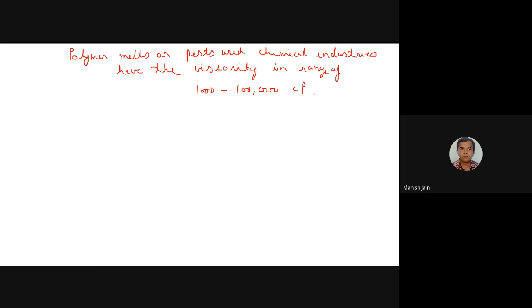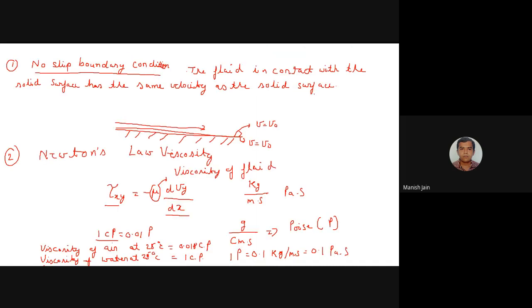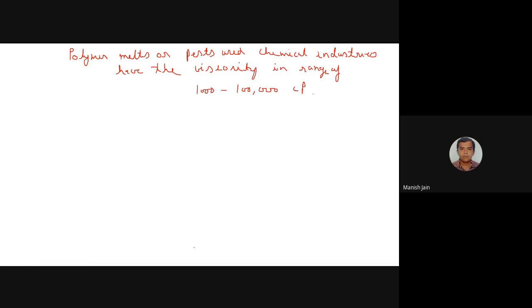You can see that the range of viscosity is huge. For air or gases it is about 0.01 centipoise, for water it is 1 centipoise, and for some chemicals it is 1000, even 1 lakh centipoise. So the range over which you study viscosity is huge.